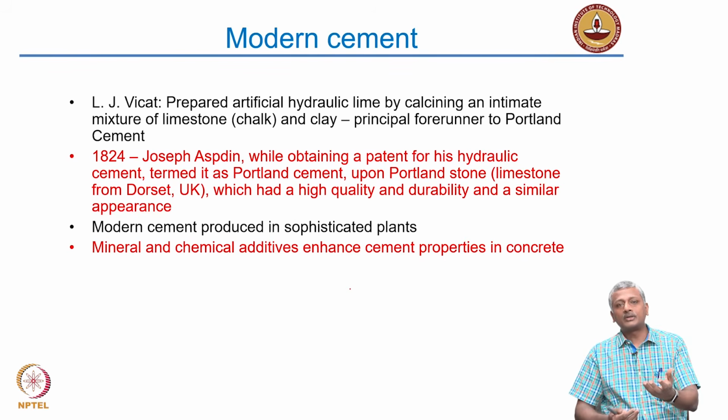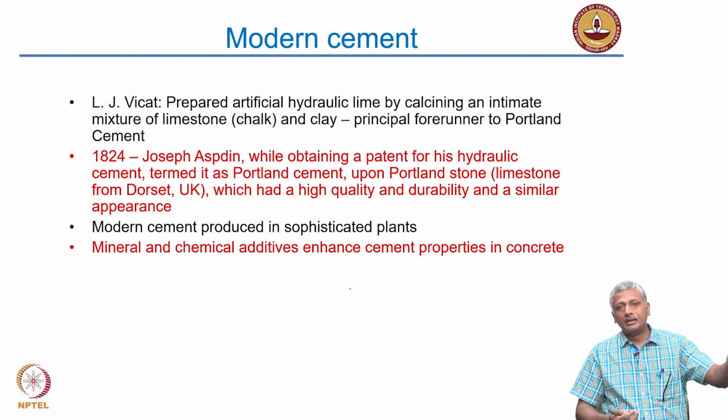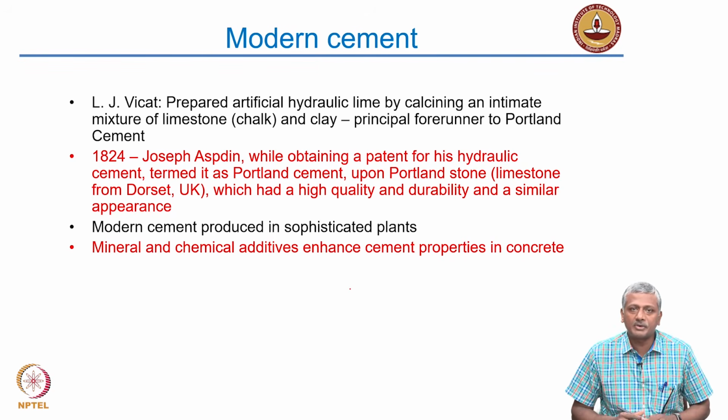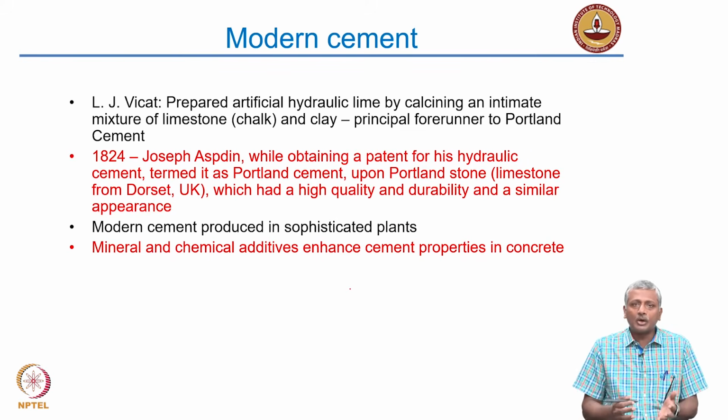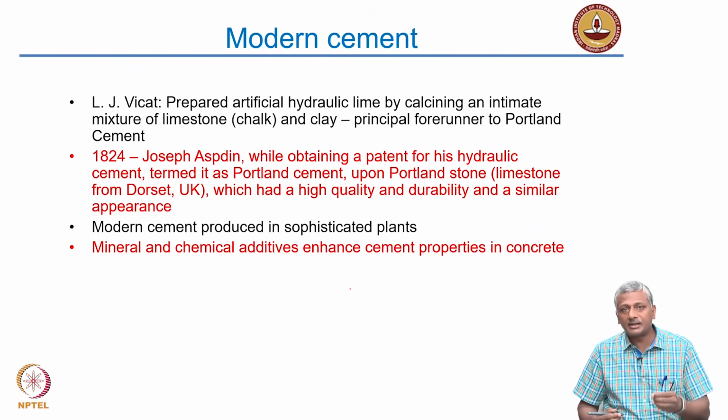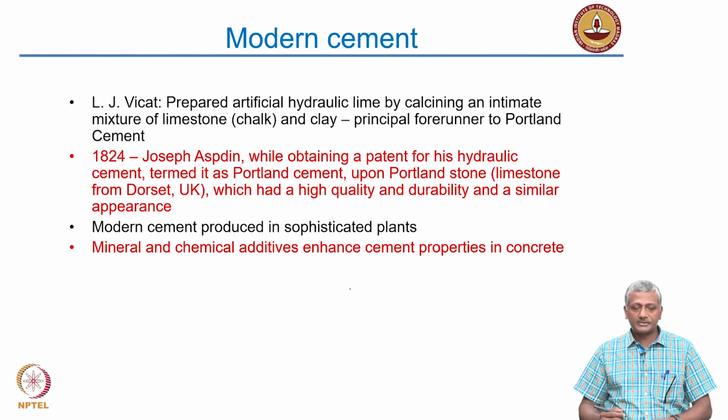So, to produce lime, what they do is they simply burn limestone. Then people started realizing, okay, if the limestone is not very pure and I burn it, it seems to be giving some very interesting properties in the mortar. What if now we take limestone and clay, add the impurity first and then burn it together? And that ended up producing cement-like substances.